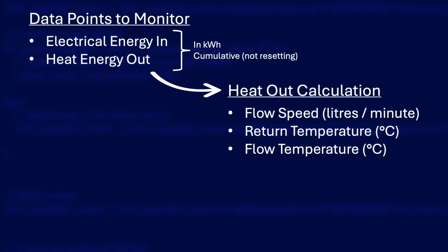Lastly, you'll need the temperature of the water leaving the heat pump, called the flow temperature, and this should also be in degrees Celsius. You'll then probably want to display the power consumption of your heat pump too. I get this from my Shelly EM, and the value must be in watts, not kilowatts. If you have a sensor in kilowatts, then you'll need to convert it to watts first.